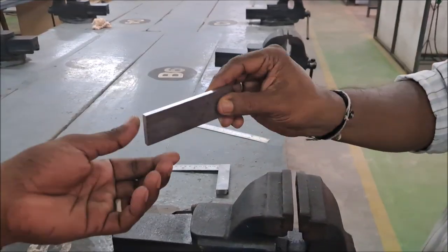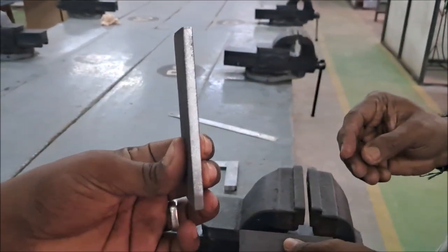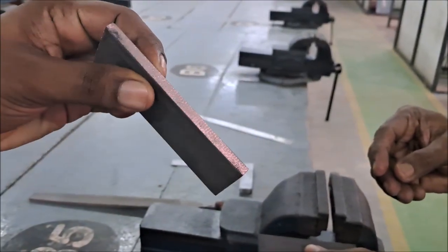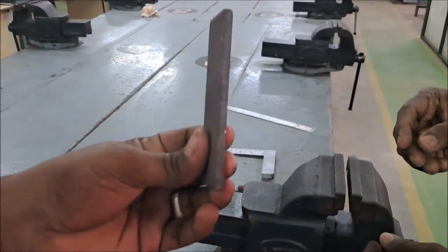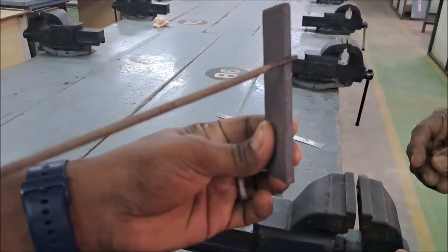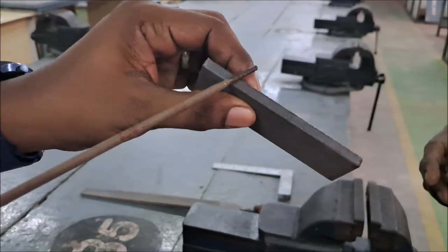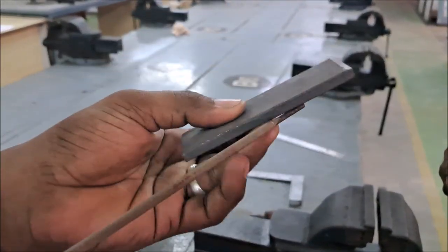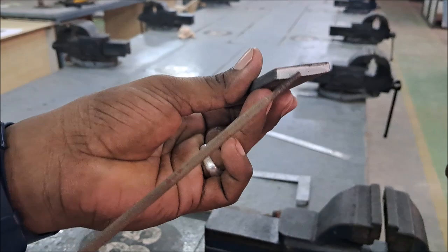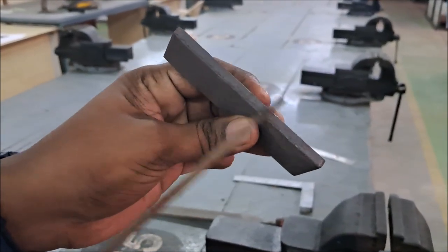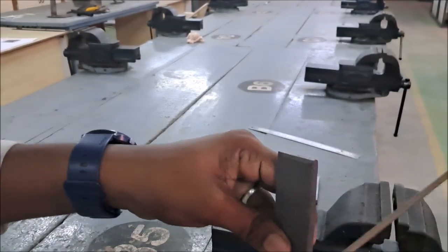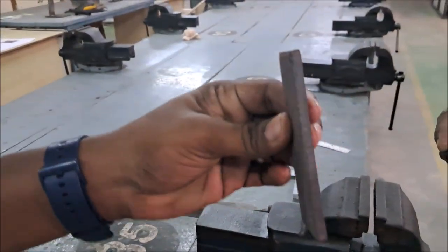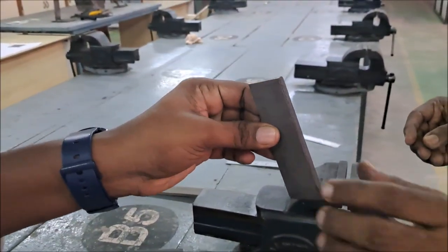Now see the difference. This is after filing. See, the workpiece has a flat surface on all sides. This is the raw material. See, the surface is not flat, because the vendor cut the material by a machining process, so many scraps and splinters are there. So when using the filing, we get the flat surface. Already one workpiece is completed. With the same procedure we can hold the workpiece to make it 90 degrees.